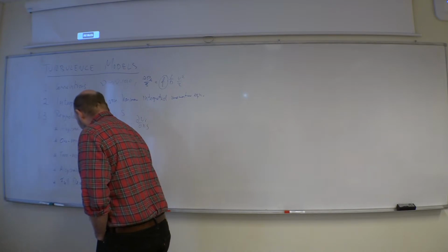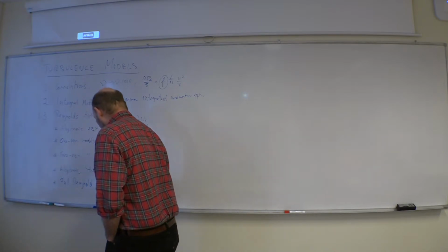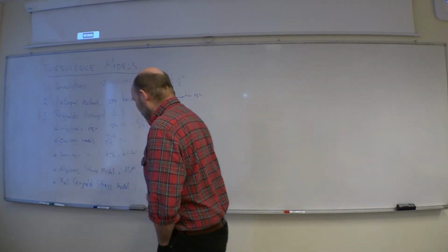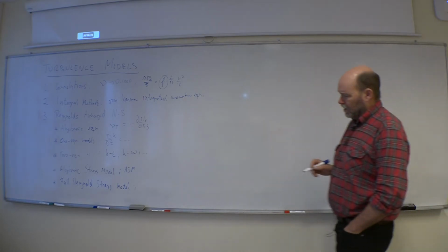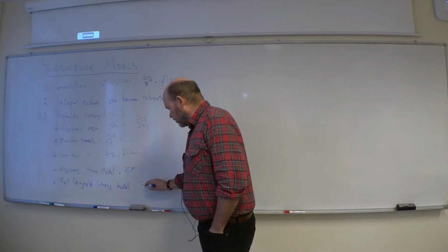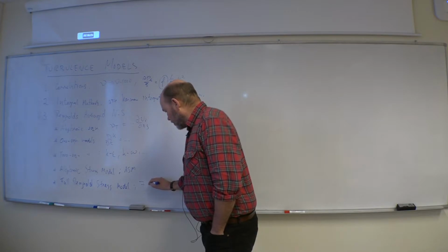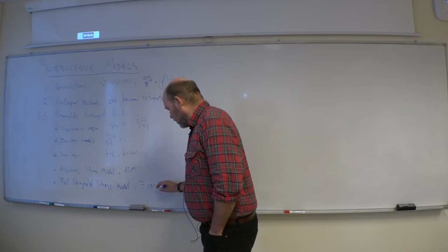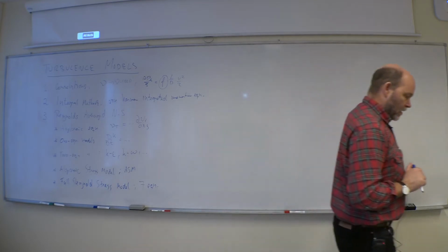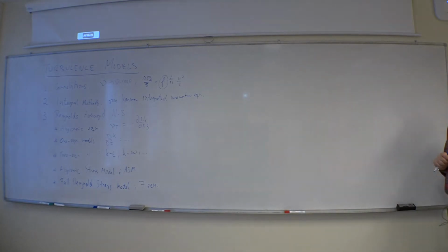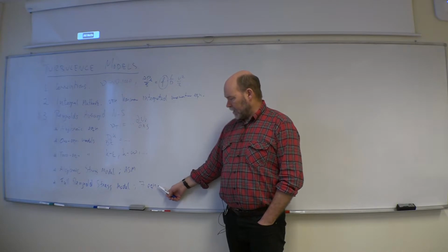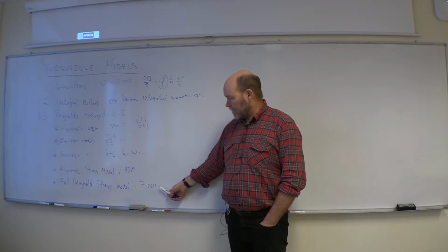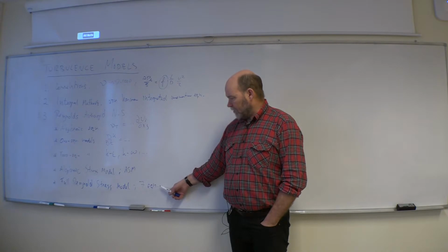And in general, a full Reynolds stress model will be 7 transport equations. 6 for the different Reynolds stresses and 1 for the dissipation. So there you are talking research. That's rather heavy, both numerically and a lot of modeling to handle these. So very, very tough indeed.